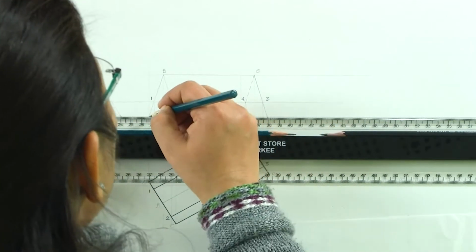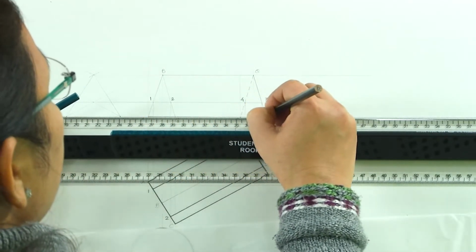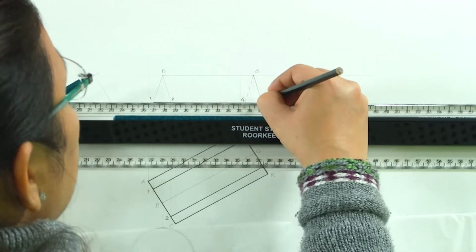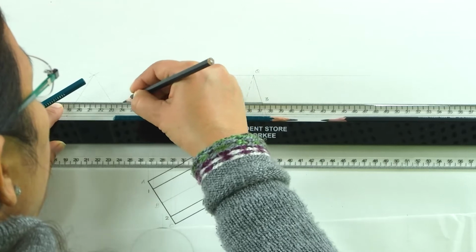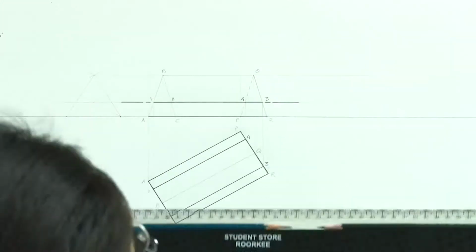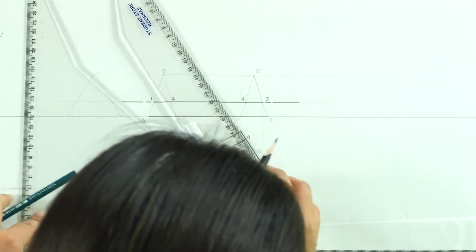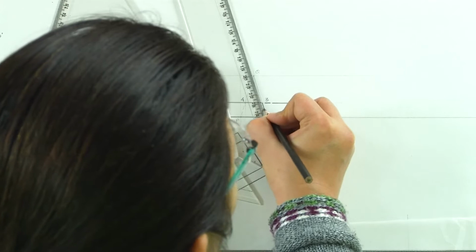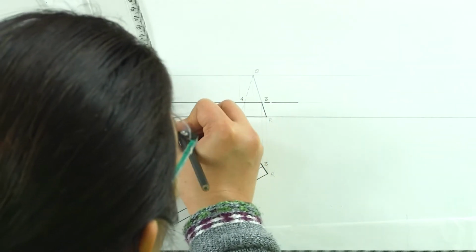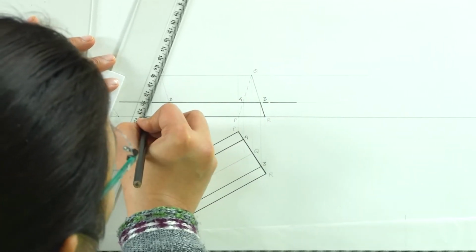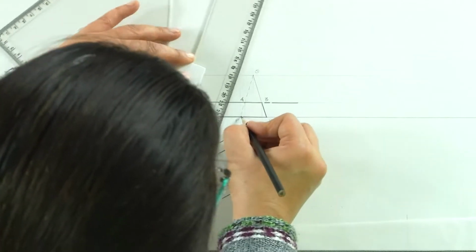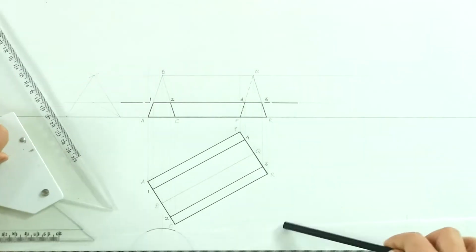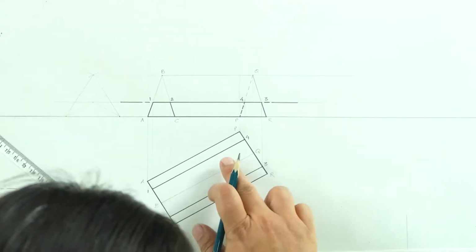Let us draw the front elevation as well. This is the section plane. Don't get confused by axis, because when we draw axis, we draw a long dash and a dot, while when we draw the section plane, we draw a long dash and a small dash. So, this is the section plane. This is the final view of the section solid. And where do we see the section? So, this is the section plane.